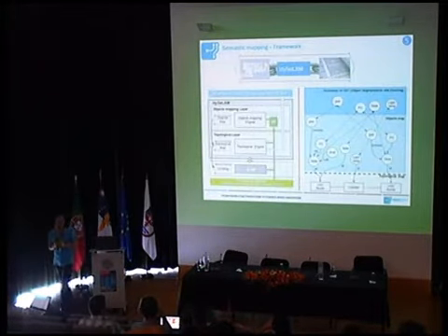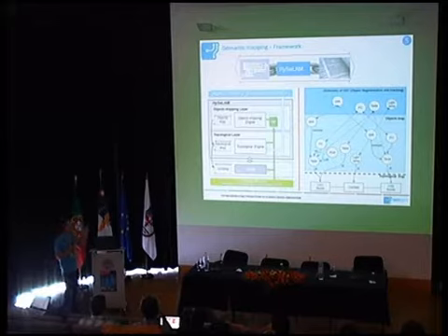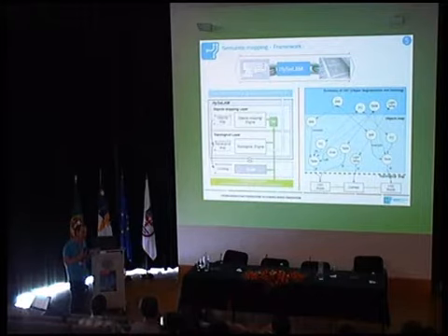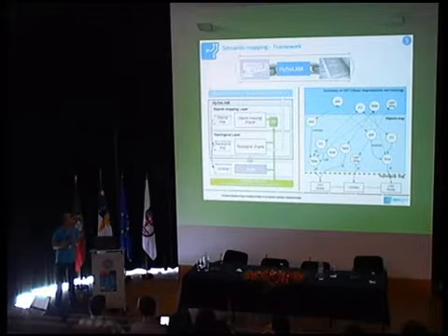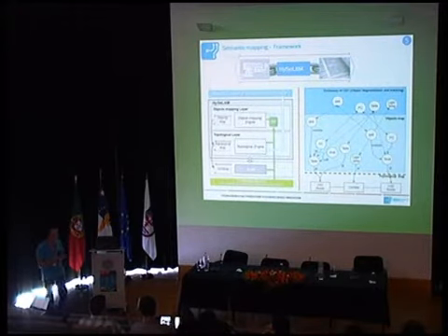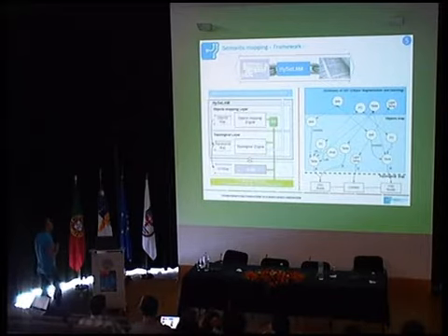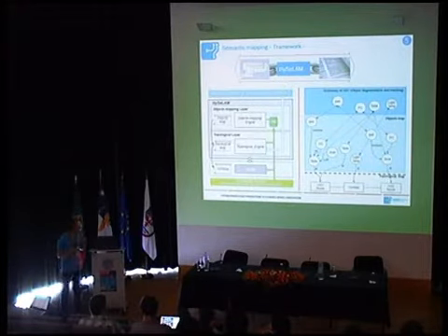Looking at that work, I think this should be improved, and we have suggested another framework where we include the object in the layers after the place description layer. What I mean is, we have an occupation grid map obtained via a common SLAM, and then another layer where the places are described, where we have a topological map. Then, connected to this topological map, we have an object map.